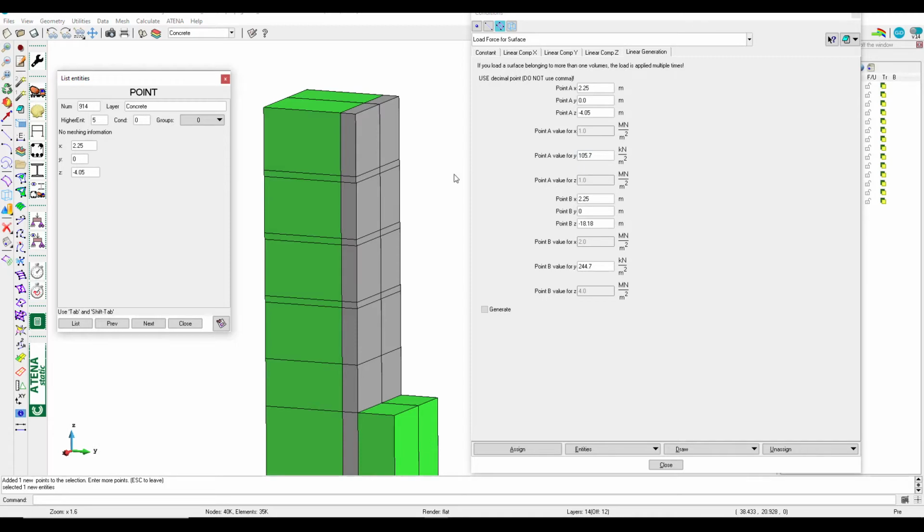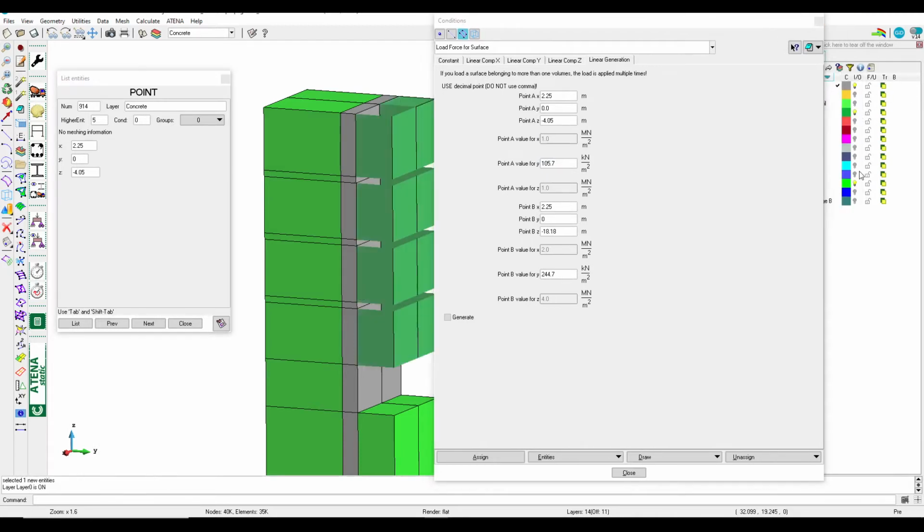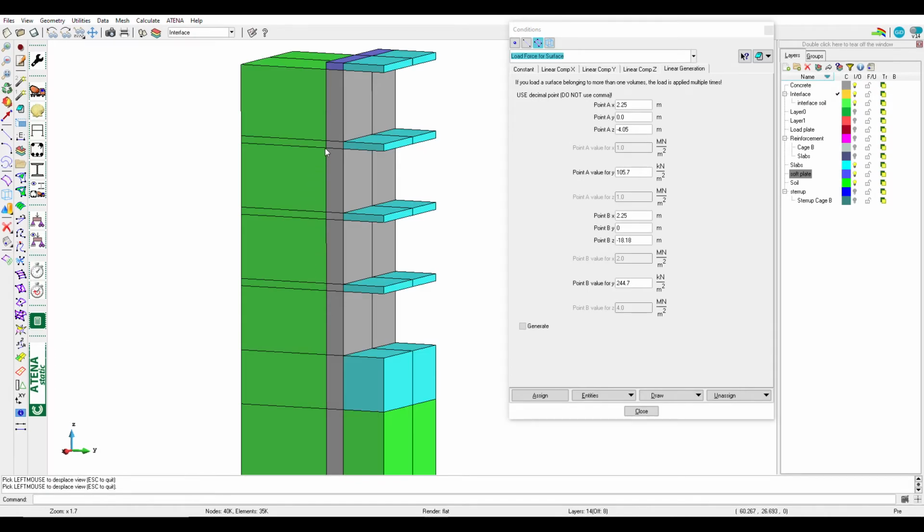The coordinates for the second point, we can define in two ways. The first way is to define the coordinates of the point at the same level as the plate P2, know the value of the water pressure there and define it. Or in our case, we had the value of the water pressure at the end of the excavation process, so it's at the end of plate 5.